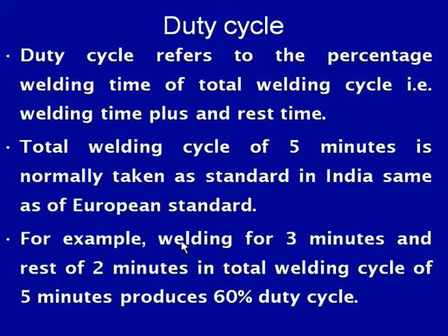For example, if we are drawing the current for 3 minutes for performing the welding, and 2 minutes is the rest time, then the weld cycle time is 5 minutes, and we are working with 3 divided by 5, which gives us a 60% duty cycle.